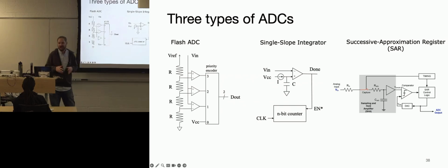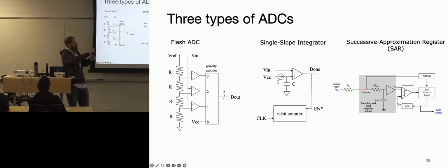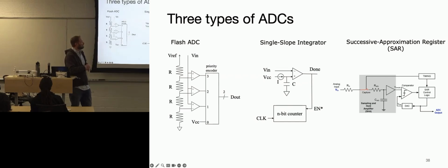There are things like parallel ADCs that try to do all the binary searching at once so that you can figure it out faster. Basically they have multiple DACs and ADCs together, but typically I just go with the worst case. Does that answer your question?